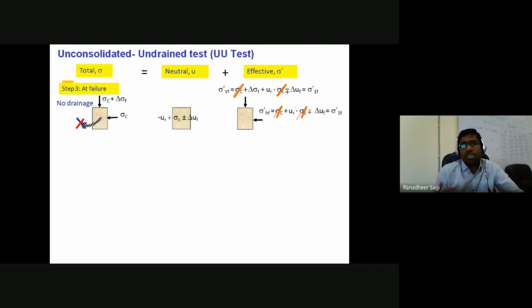So automatically your Mohr circle, what you are going to be getting in terms of the effective state of stresses acting on soil sample 1, 2, and 3, those effective state of stresses are going to be same, because it is independent of your applied confining pressure.